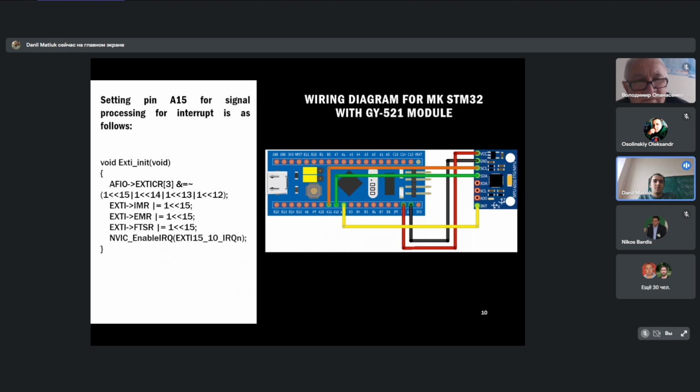The MPU 6050 has a programmable interrupt system that can generate an interrupt signal on an INT pin, which generates a pulse every time the state of the pins changes. In the figure, pin A11 is responsible for clocking the I2C bus, pin A12 is for data transfer, and pin A15 is used for implementing an interrupt to fill the memory buffer in the MPU 6050.